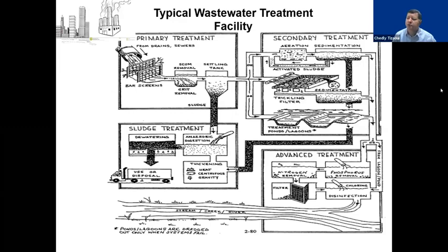That would involve, for example, trickling filters. Basically a trickling filter is a filter where you have stones, and on those stones' surfaces you let the bacteria grow. When the water passes through those biofilms, as we call them, of bacteria attached to the surface, you have the treatment.